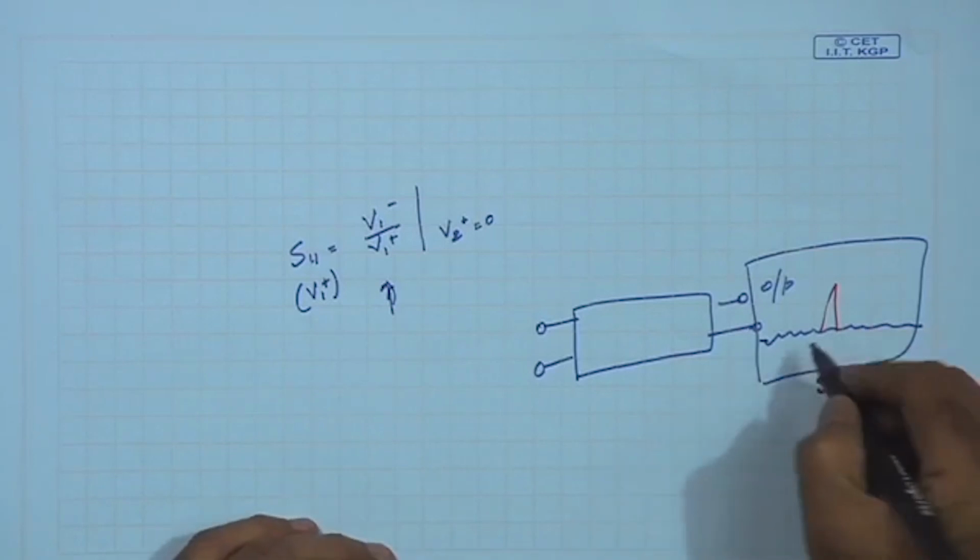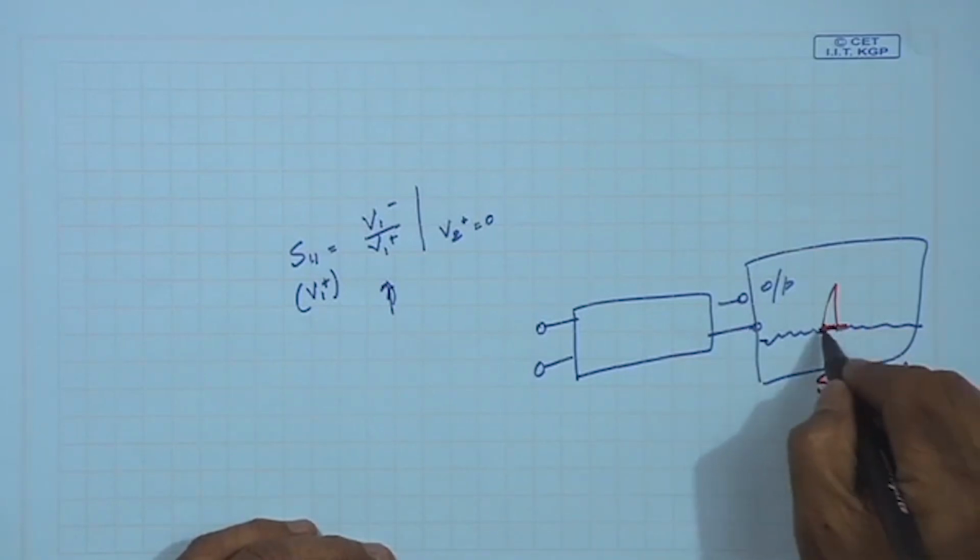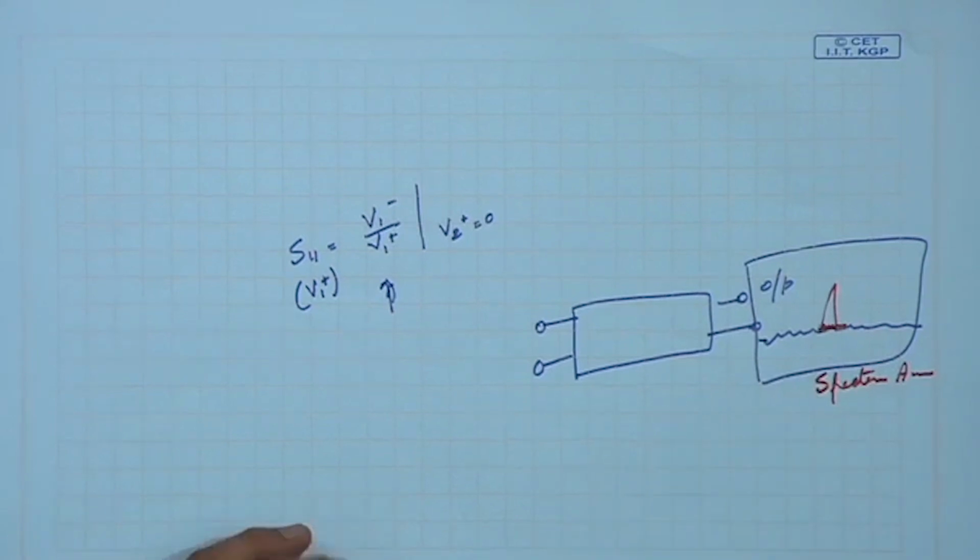Now, my signal should be sufficiently above that noise floor, actually several dB up from that noise floor. So the minimum usable range is always the noise floor plus some extra dB, so that I can recognize it as a signal. Because if my signal is like this red one, I will not be able to recognize it as a signal, even though it is a signal. So the minimum level of input signal should be sufficiently above the noise floor.